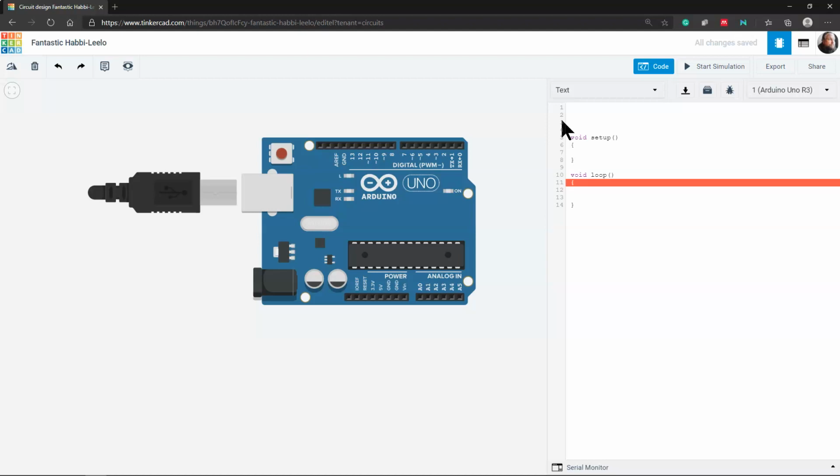Now I'm going to do this in two different ways. One where we're just going to use the Arduino to get power and not use any of the actual GPIO pins to do work for us. So just kind of recreating what we had from that first circuit, but we had hooked it up to a 9-volt battery to get the power. But instead now we're going to use the pins that the Arduino offers to provide us power and just get it to go on. And next, we're going to change it so we can take that same circuit, hook it to a pin, and then use that pin as a way to control what happens to that actual light. Basically making an on-off switch and doing different work.